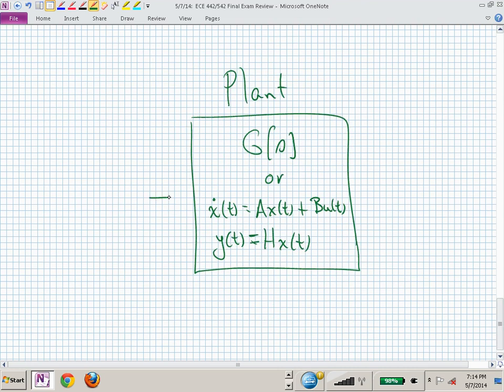Then you can't just apply a sequence of numbers to this analog system. It won't behave properly. You need to convert that sequence with some hold network or device that will, in a zero-order hold, just hold constant whatever it was that you supplied at the input. At the input to the zero-order hold, if you gave it a 1.7, it's going to hold that for one sample period.